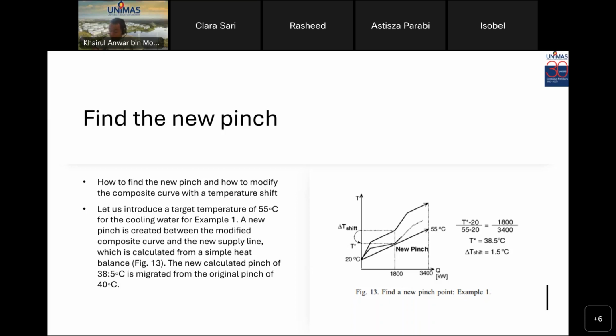The second stage is to increase the flow rate of the limiting water profile when the shifted profile is restricted by the temperature limitation. The limiting cooling water profile is modified to satisfy temperature limitation by increasing the cooling water flow rate.